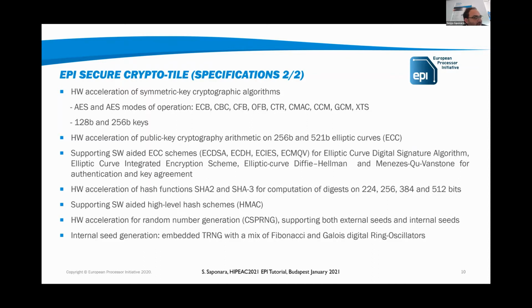Just to give an overview of the performance that you can achieve, for example, for symmetric cryptography, AES modes are supported. There is an AES core, but then you have multiple modes of operation. Up to 9 modes of operation are supported, which are de facto all the ones used. Also, in terms of key extension, in order to be ready for post-quantum cryptography, the classical key of 128 bits can be not sufficient in a post-quantum domain, so we already support an extension up to 256.